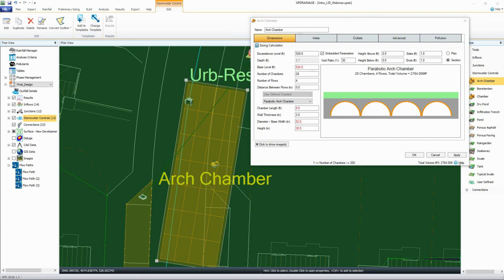Now, that might seem like a burden. Well, that means the heavy metals are getting trucked somewhere that's a designated zone for it, as opposed to just washing right out into my streams or into other areas, again, where my child might play. It's in a kind of quarantine zone, so to speak, in this planter box that no one's going to play in. But yes, over 15, over 30 years, those facilities may begin to accumulate beyond just sand and grit. That's something you'll probably see visually and be able to maintain. It's the unseen stuff, really high in phosphorus, really high in heavy metals from brake pads.